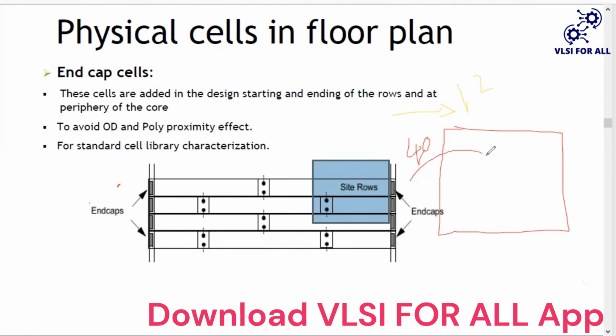Total 40 macros in the placement stage, and you placed only 36. The remaining 4 macros are outside the core area, behind the core area. If macros are behind the core area, we call them unplaced macros. Or, if all 40 macros are placed inside the core area but a macro is not placed in the site row, we also see it as an unplaced macro. We can easily find these violations.